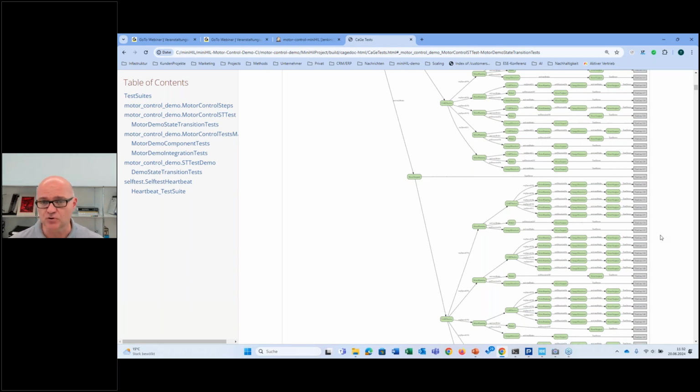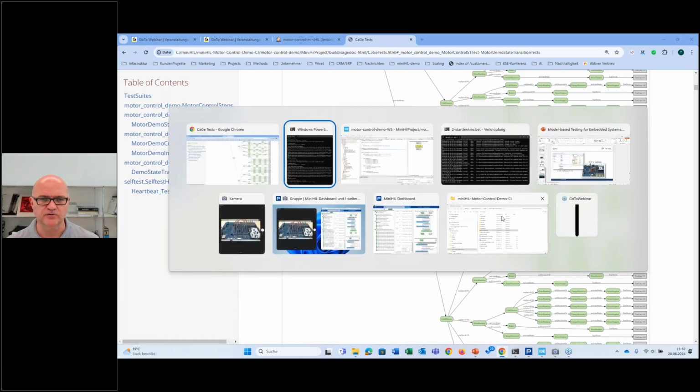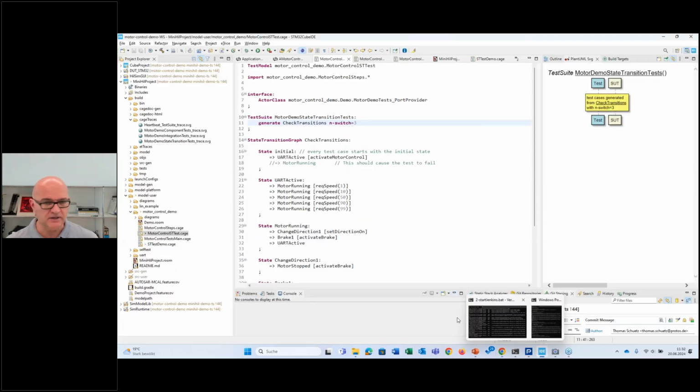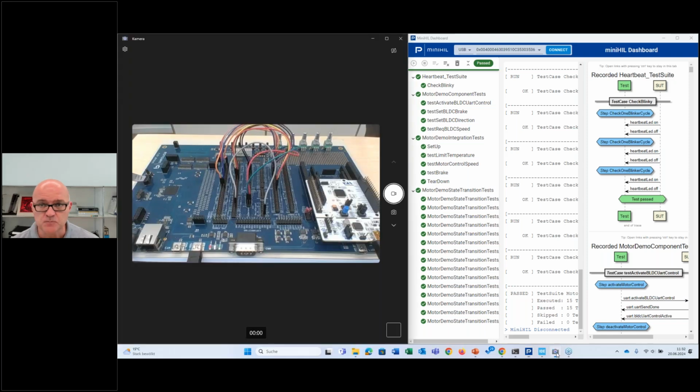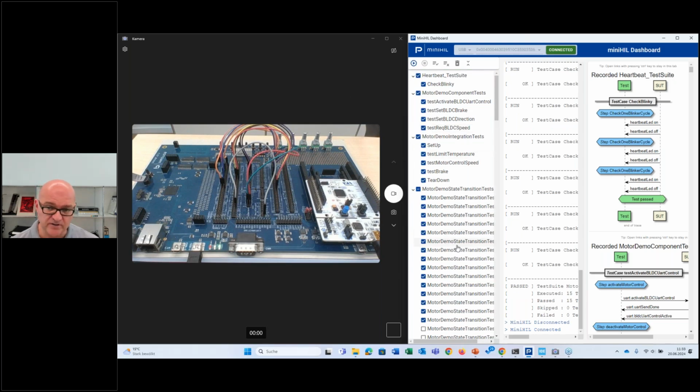And it's everything asynchronous, but in order to do this, you need the environment simulation and the code generator for those test cases here. So now, last but not least, we can run the test system. I'm connecting the generated system here with my test system. The system under test is this microcontroller. Here, see all those signals I've defined before. So UART, PWM, the Hall sensors, and so on.